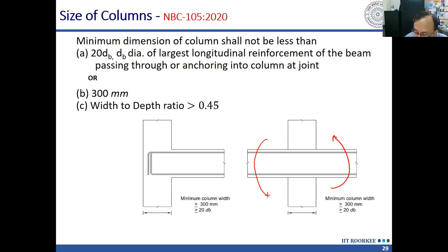either clockwise or anti-clockwise. And due to that, what is going to happen? We will have tensile force in the bottom, compressive force at the top. Here, we will have tensile force at the top and compressive force at the bottom. Now you can see in the bottom bar, both the moments are applying force towards right. So here, large shear force will act in this direction.